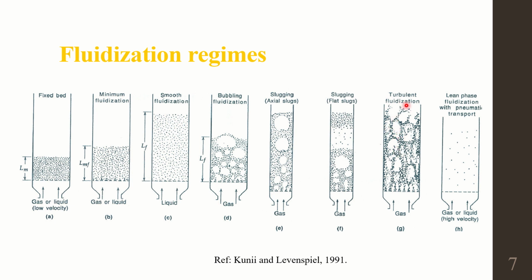Because of that, a turbulent regime is observed inside the fluidized bed, wherein a very vigorous motion of fluid is taking place, and because of that the solids are also getting very well mixed. And after a point the solids would be escaping from the bed, where the phenomenon observed is known as pneumatic transport, where the solid fraction becomes very less.